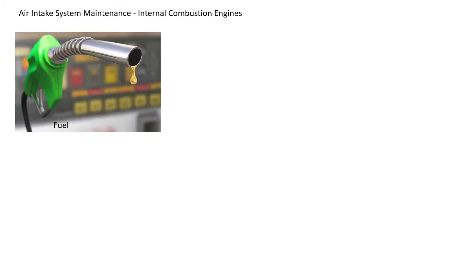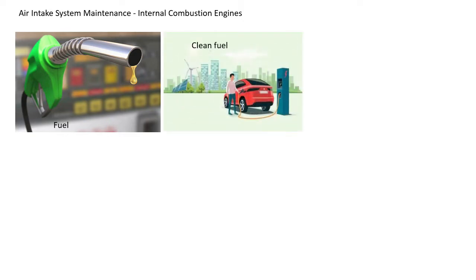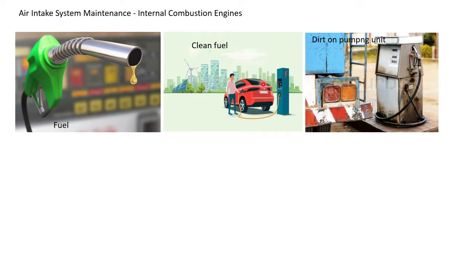Just have a look at the fuel. We must use clean fuel. That is, a clean fuel pumping station looks like this. See here the dirty fuel pumping station. This is the problem. Whatever dirt is there on this fuel pump may go along with the fuel to the tank and enter the engine fuel injection system, damaging the injectors, pump components, etc., leading to premature failure of the engine.